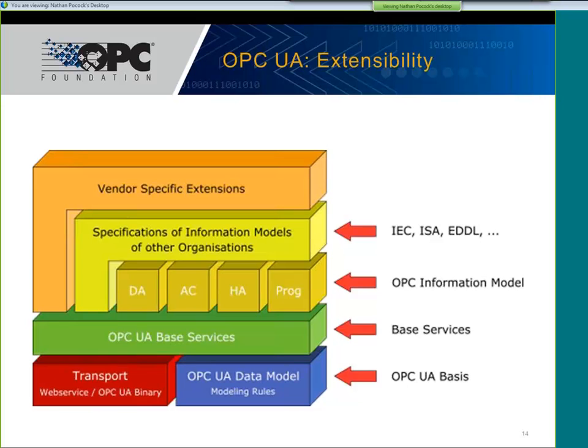In the AC, it will grab the different data types it needs from the blue box and the different methods it needs from the green box, and now that's the AC equivalent, or the alarms and events condition equivalent from Classic. From the L-shaped boxes, you can see that the model is extensible, so you can just layer your different information models and profiles on top. This is what's going to allow new specifications to be developed over time without breaking existing specifications or different applications that already exist.